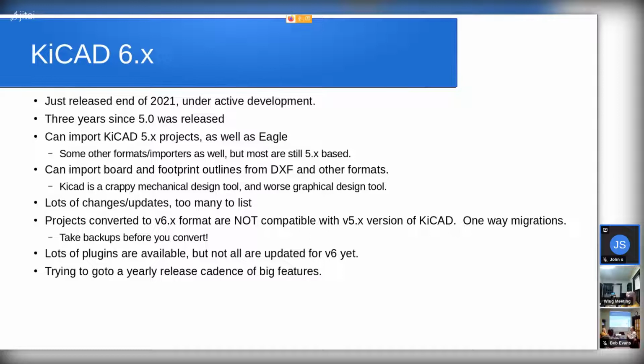In that case, what you need to do is either design it in a CAD program or in any program such as the one that draws vector pictures, Inkscape, that can then export in the DXF format, which is the AutoCAD format. If you can do that, KiCAD can import that and turn it into your outline, your board edge cuts, and you can do really funky stuff with that.